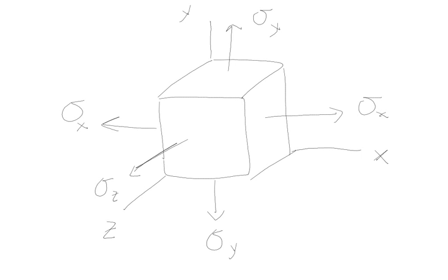So think about what this really means. If I take a cube and submerge it in water, you put it in a bucket of water, then that water pressure pushes equally, or more or less equally, on all 6 faces of the cube. And that cube is going to end up shrinking. That means it gets compressed in the x, the y, and the z directions. It's going to have compressive stresses in the x, y, and z directions.